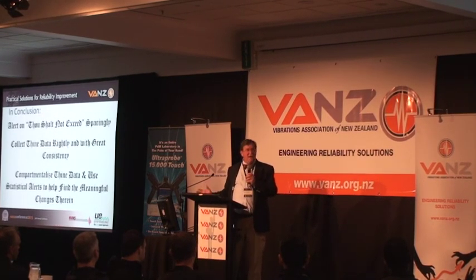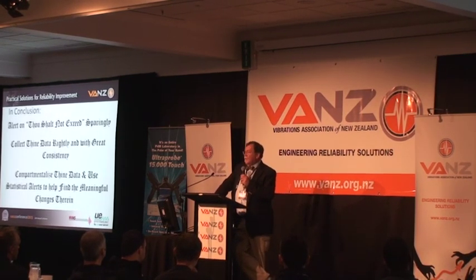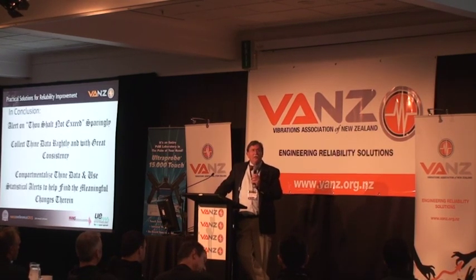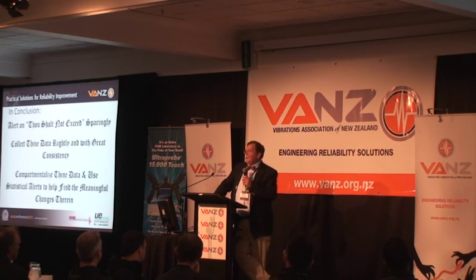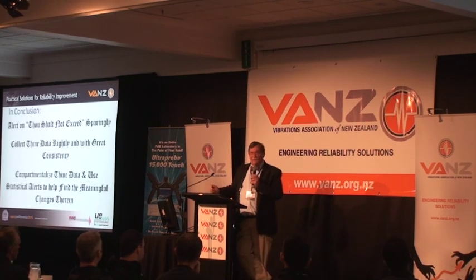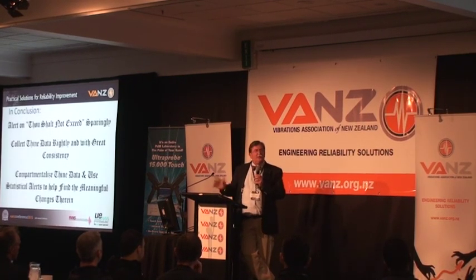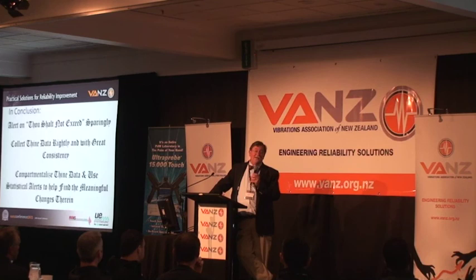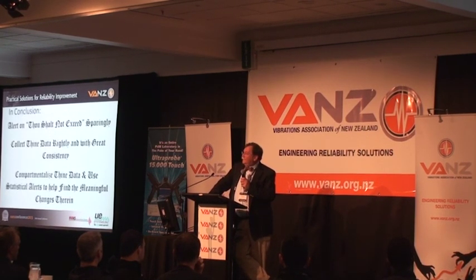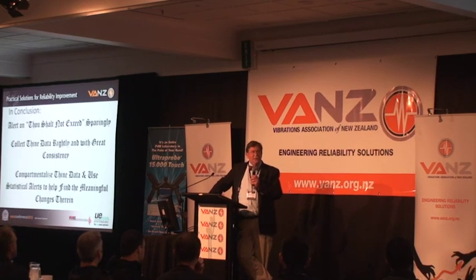We immediately notified the other plant in the U.S. that had two of these identical machines, and during their next refueling outage, they popped the hoods and pretty much found the same problem developing on their units. And they did the same thing we did. They pulled out all the fourth-stage blades on both sides of all three of their, or actually all six of their low-pressure units, put in blanking plates, and used the same manufacturer we did to create new blades.